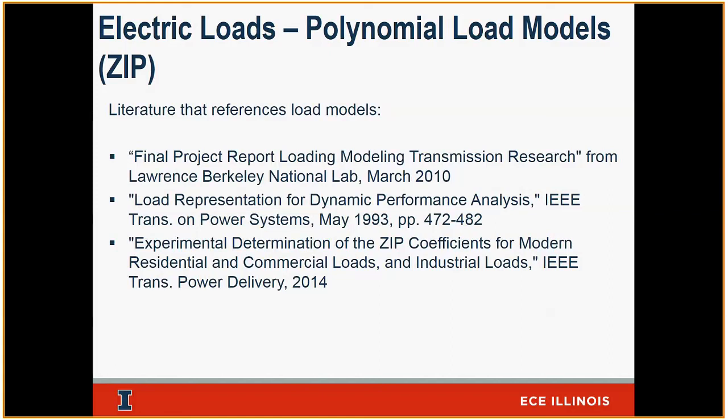So first we got to get a complaint, right? So again, we don't have a lot of resolution on this. Somebody has to complain, and then typically what we do is start investigating. We put a power quality meter right at that customer premise, so at the industrial customer premise.